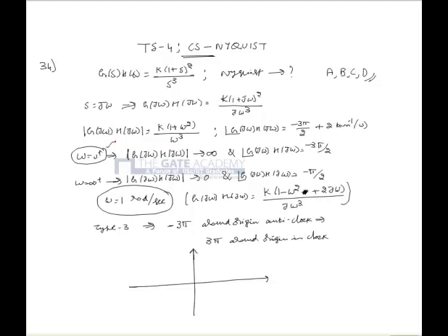At omega equal to 0 plus magnitude is infinity and phase is minus 3 pi by 2. So it starts from here, and at omega equal to infinity magnitude is 0 and phase is minus pi by 2, and it approaches origin from this direction. Also, the Nyquist plot intersects with the real axis for omega equal to 1 radians per second. So the Nyquist plot for omega equal to 0 plus to infinity can be drawn as shown.